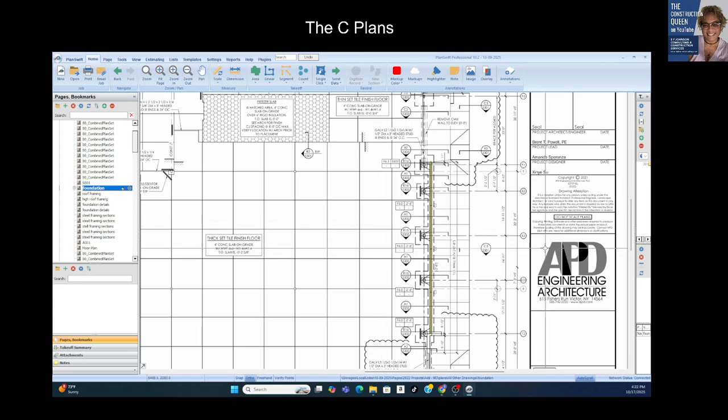Now, if you had to take a framing takeoff, and I said, what is the typical way to do it, let's start with the foundation takeoff to get everything you need. Now, this is the way that I do it, because I know that the slab on grade is what it is. It's a big square. That is the easiest thing to do if you have an area tool. Boom. It's 4 inches. You know the area. That's the easiest thing to do.